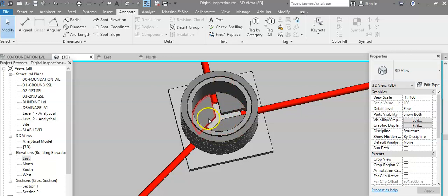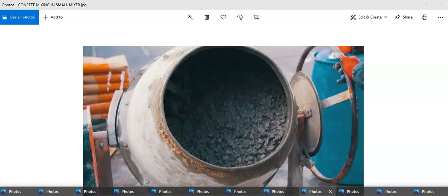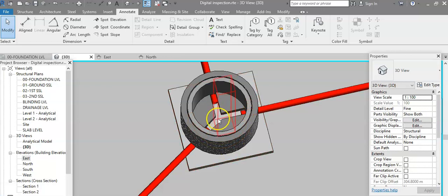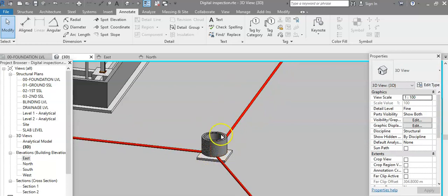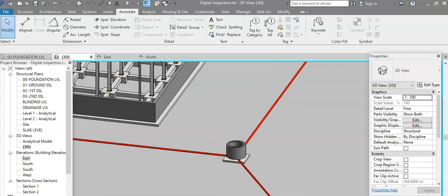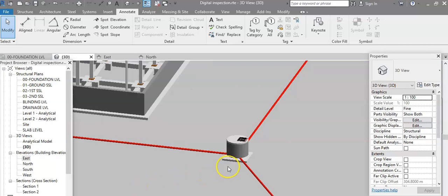The benching is a concrete which they mix on site, but they use a finer stone, or they just use sand and cement with some chemical material to mix it and to make all these shapes for the flow of the sanitary. The flow will go from one end to the other. We call them channels. So now this manhole is being built, and all these items are being placed ready.